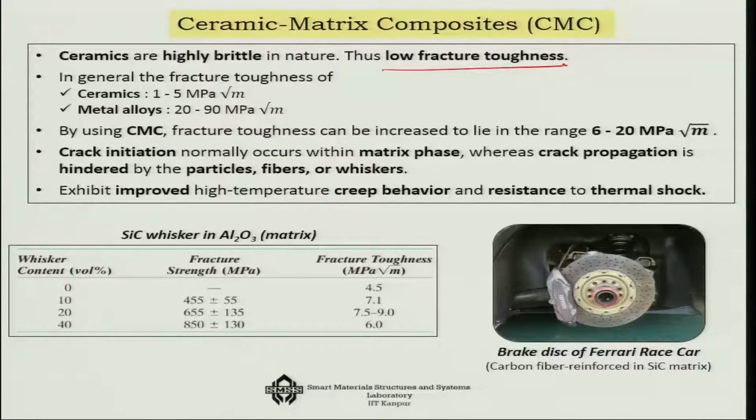In fact, to handle the ceramic fibers, we do something which is known as sizing. Sizing means you take a ceramic fiber and then you apply an oil coating over it. Okay, and what coating you are giving, that is a trade secret, because that enhances the life of the fibers and that increases the fracture toughness.